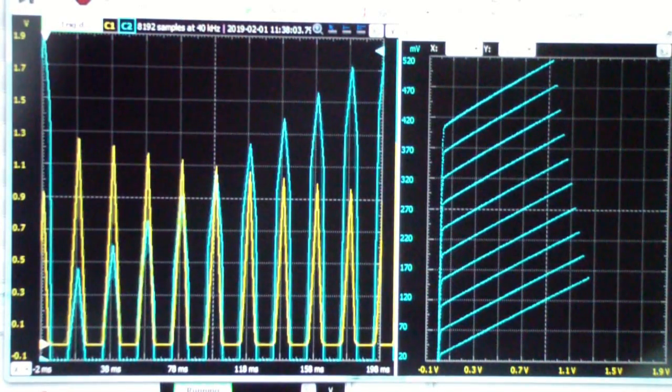For those of you that have followed the development of this curve tracer using the Analog Discovery 2, this is a yet further improvement to it. I thought it might be handy to show you the state of the curve tracer before the improvement, and the improvement is to add a current mirror to the circuit in place of the 100 ohm sense resistor.